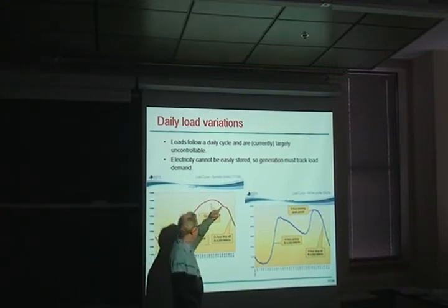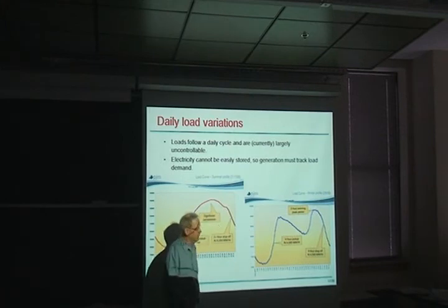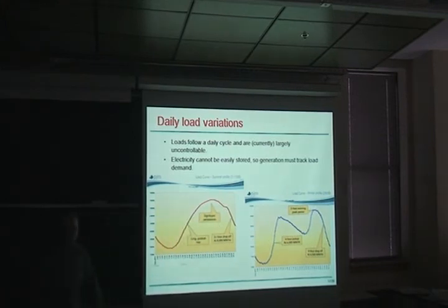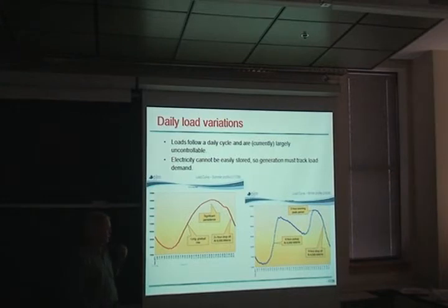You see this little kink, that's people coming home and doing their cooking and televisions on and all that kind of stuff. Overnight, so here's 3, 4 a.m., the load drops way off just when the wind is picking up maximally. And so this is a real issue for power system operations. This is the perfect place where storage would be very valuable, but to store a significant amount of energy, when you're talking gigawatt hours and above, that's a lot of capacity.